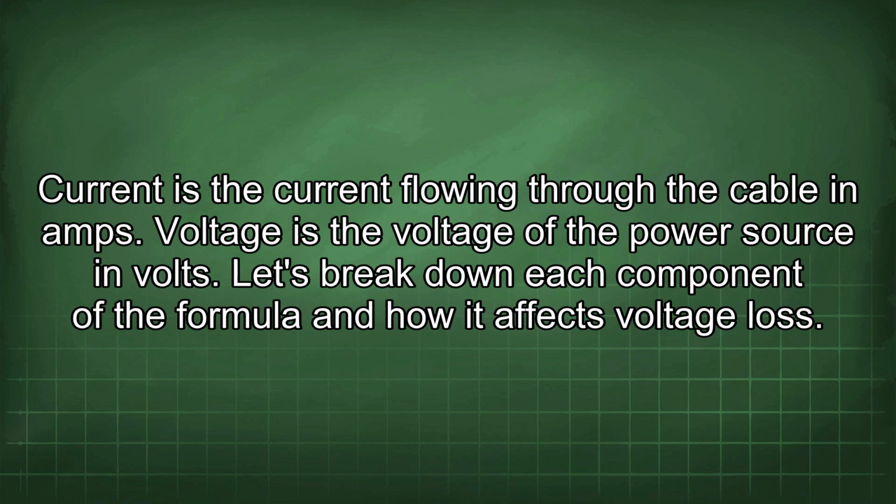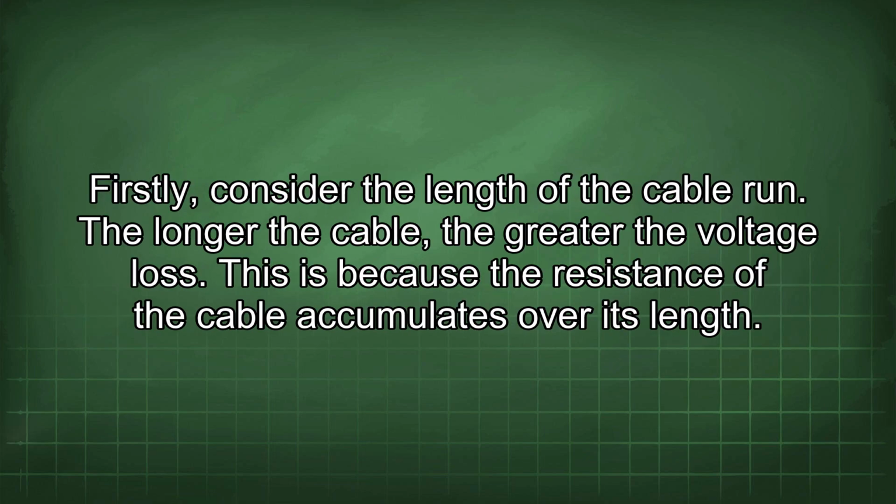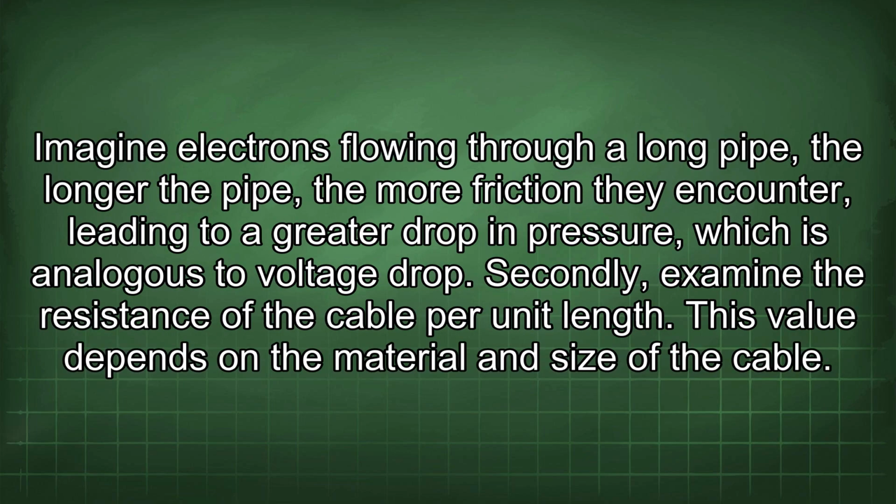Let's break down each component of the formula and how it affects voltage loss. Firstly, consider the length of the cable run. The longer the cable, the greater the voltage loss. This is because the resistance of the cable accumulates over its length. Imagine electrons flowing through a long pipe. The longer the pipe, the more friction they encounter, leading to a greater drop in pressure, which is analogous to voltage drop.